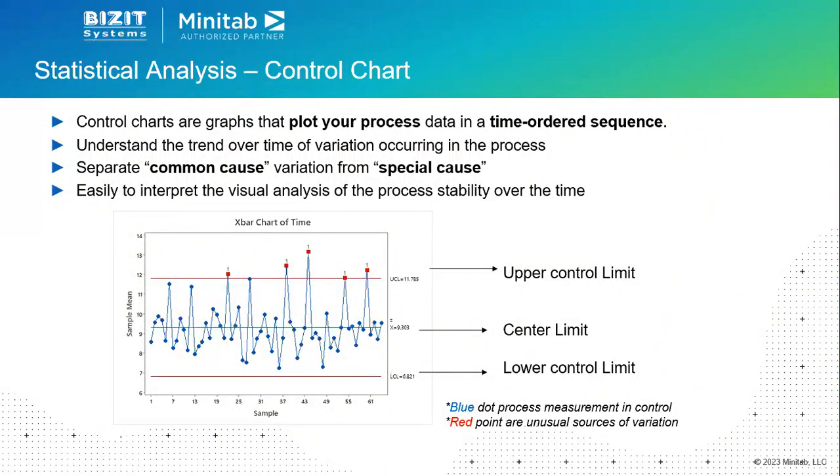So they provide the data, and we try with the control chart. Basically in the control chart we want to see the common cause and the special cause. Just now on variability, in the plot, you can see whether there is variability or not. Variation can be 2 kinds, common cause or special cause variation. So to identify which one it is, common or special cause, you need to use the control chart.